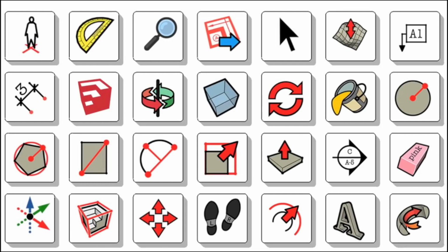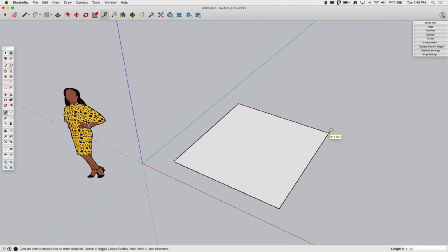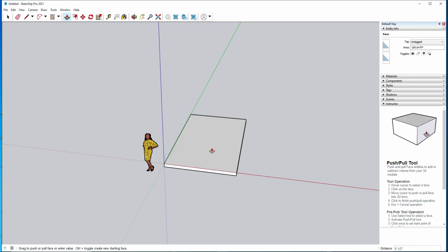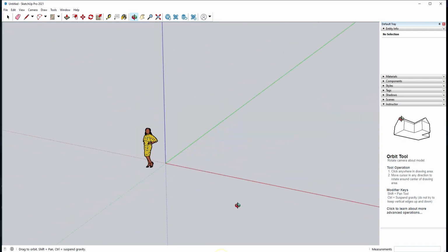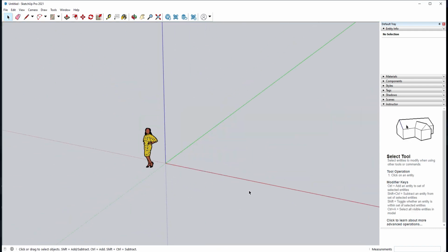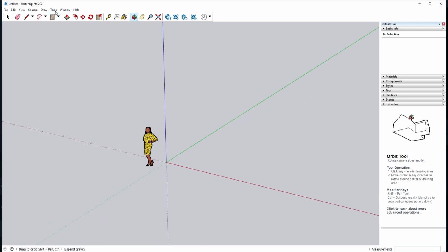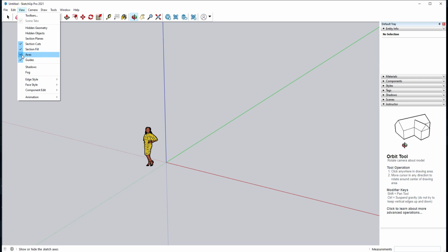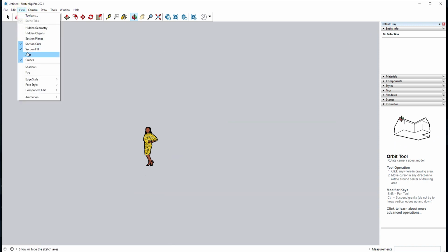SketchUp screen. Drawing and editing tools. These tools create geometry, line, arc, rectangle, etc., construction objects, measure and protractor, and enable object manipulation, move, push-pull, rotate, etc. Drawing axes. When you open a file, the model contains a set of red, green, and blue axes. These are equivalent to the X, Y, Z axes used in traditional CAD software. You can turn off their display by selecting View, Axes, and the Axes tool can be used to relocate and reorient the axes.